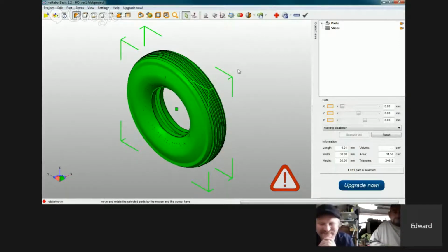Okay? And people say, well, why not let them do it? I say that's if you want to. I like to have more control over my own modeling than let some piece of software, I don't know where it's at, do it, right? If possible. Sometimes you want to be able to track down where the issue is, and if you let automated features take care of things, you'll have a ton of problems tracking back to it. Okay. In other words, I took out those duplicated vertexes.